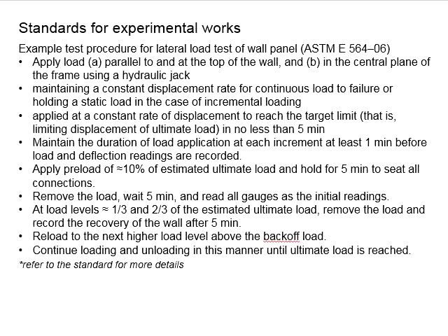For those who have experience with the experimental test, once you increase the load, you will see some fluctuations of the readings. You will have to wait until the readings more or less stabilize before you can record the reading. Otherwise, the readings that you have acquired may not be accurate.